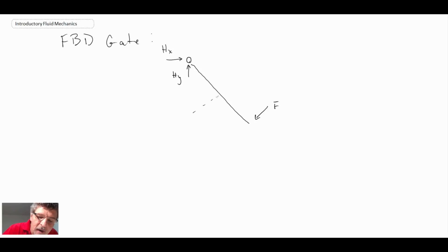Well, let me draw. This here is the center of area. And we also have, yet to be determined, the center of pressure. And that is where the force due to the fluid is acting, and we call that force Fr. I'm drawing it normal. It is going outwards, and so that is the free body diagram. XCP we have not yet determined, but that would be XCP, YCP for the center of pressure.